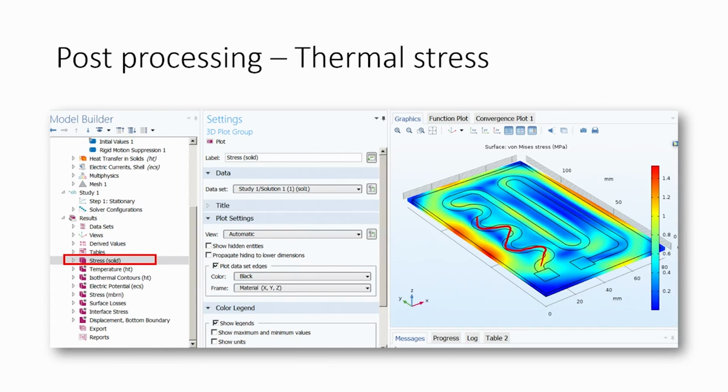And this is a plot that you can see here where the stress at the end of the chip is extremely less compared to the heating substrate, and this stress is because of the expansion, here as well as on this particular area. Now, this is about 0.8 compared to the almost 0.1 or 0 stress at the edge of the chip. Now, there cannot be 0, there will always be some amount of micro stress, and this stress is given in megapascal. So, the one that we are showing here is somewhere in the megapascal range.